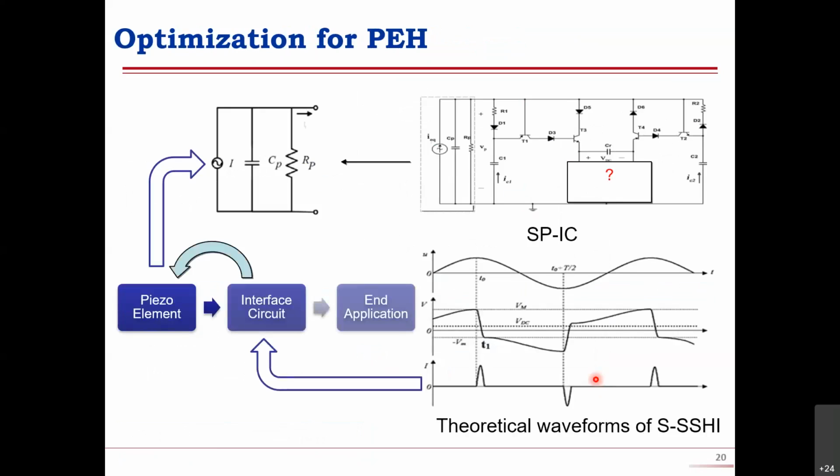Okay, and for the optimization of the PEH in the future, I think we should carefully consider the coupling between the piezoelectric elements and the interface circuit, because this interface circuit will affect the PZT current output a lot, since it will affect the vibration and the electric field on this PZT.